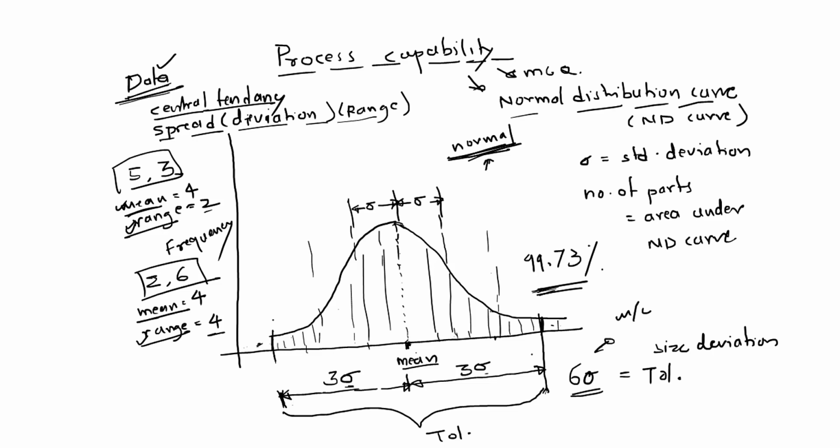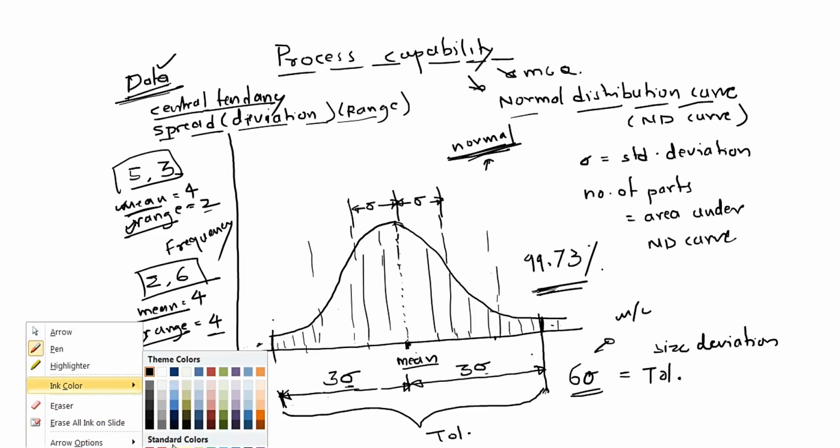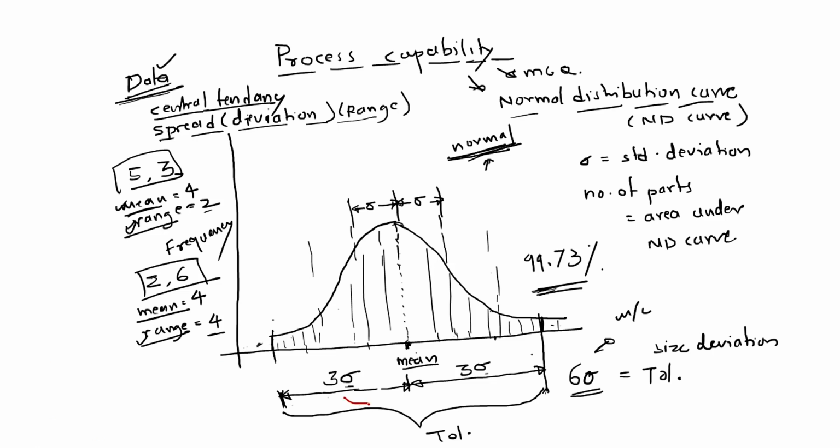But if I shorten the tolerance, if I make the tolerance smaller, only this much, that means only this is the accepted parts. All those parts are rejected. These are rejected parts in that case. That means a larger number of parts are rejected. 1%, 2% is allowed, but more parts are rejected. Still, this much accepted part is not worth running a factory. There should be less rejection.